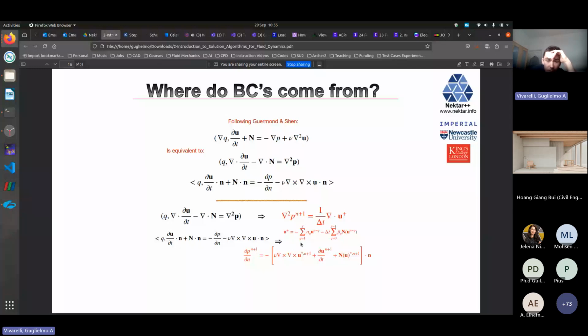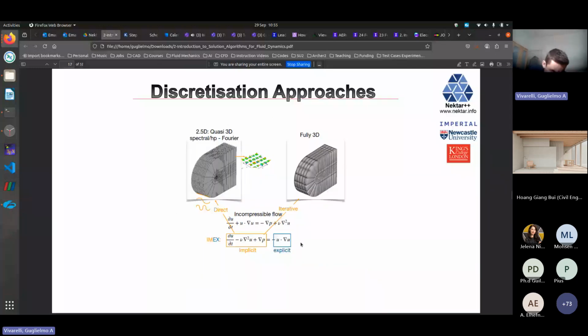Okay, so one thing I wanted to bring your attention to, and I mentioned earlier on, was the Fourier expansion utilized in homogeneous domains. A homogeneous domain is simply a 2D domain that is extruded in a homogeneous fashion in the Z direction. You can put symmetric boundary conditions at the end if you want, but you normally end up putting periodic ones. With periodic ones, you can use a Fourier expansion that allows you to solve it in roughly half the amount of time, or half the amount of resources, very roughly, with respect to a physical extrusion.